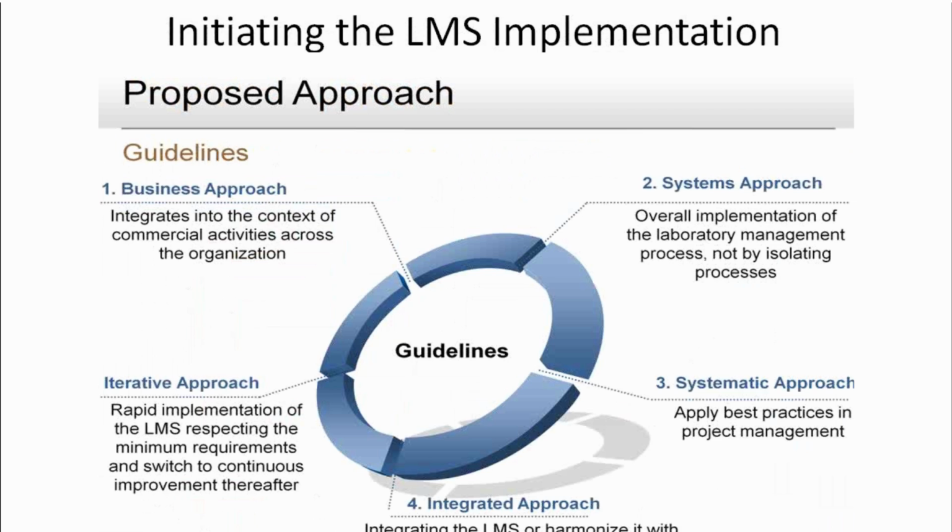Your report should also carry identification of the method used. You are using an ASTM method, you are using a US EPA method. There should be a note of any deviations from a standard. There should also be the results part, which will carry the units. It's also advisable that there should be the name, position, and signature of the person accepting responsibility for the report.